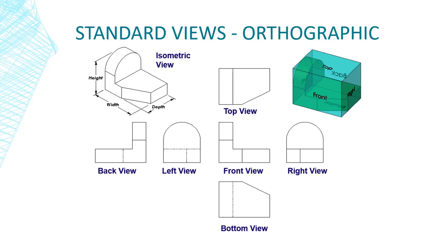But that doesn't mean whatever you have developed on the front plane must be the front view of the drawing. Fusion 360 and all the other CAD modeling software allows you to bring your model into the drawing area and you can label it as you like and reorient and automatically create the corresponding projections, so you can add the dimensions as you wish.